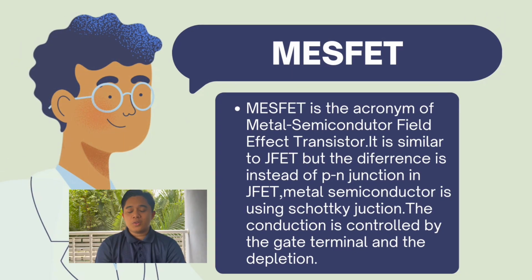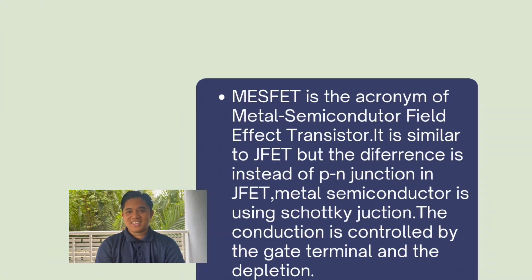Then I will continue to my part, that is MESFET. If you want to know, MESFET is the acronym of metal semiconductor field effect transistor. It is similar to FET, but the difference is that instead of a PN junction as in FET, the metal semiconductor uses a Schottky junction. The conduction is controlled by the gate terminal and the depletion.